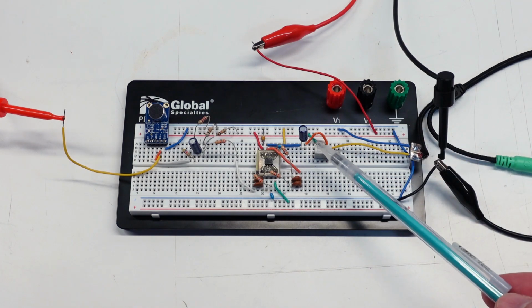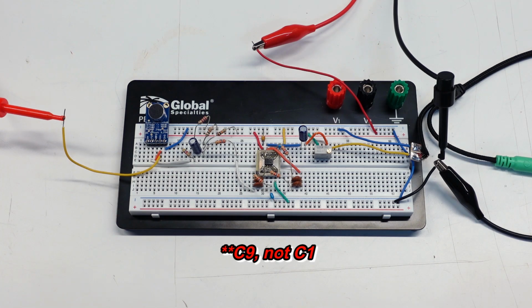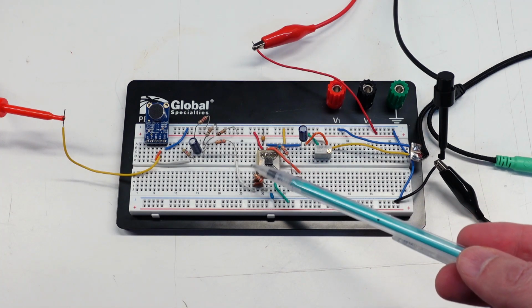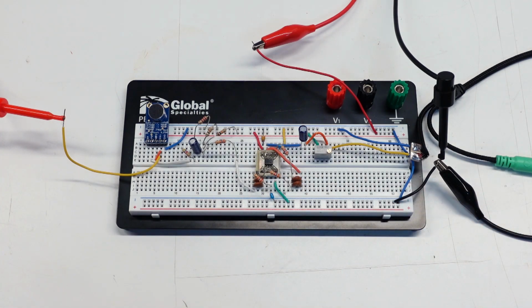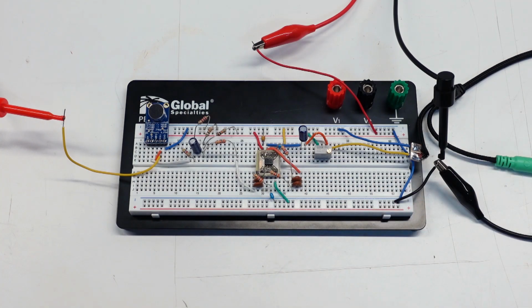It's all connected up to this very simple connection. Now here's that 20K trim pot still, that'll lead through this connection to my laptop so I can record a sample of what the audio sounds like. Now I don't have L1 or C1. Those were on the input side, if you recall, on the schematic that I showed earlier. In particular, L1 was a 100 microhenry choke to help filter out any RF that might be there. I don't need that for this quick test, but nonetheless, the rest of the circuit is here. So let's give a listen to what it sounds like.